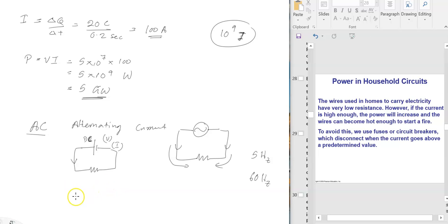So let's say there's a wire and goes to this light bulb over here. This is a power cord connected to the outlet. These wires have some resistance, right? And if you try to draw too much current, we can find the power using this equation, I squared R. If there's a lot of current in this, I squared increases, the wire itself is going to emit a lot of power as heat energy. It can heat up and then create problems.